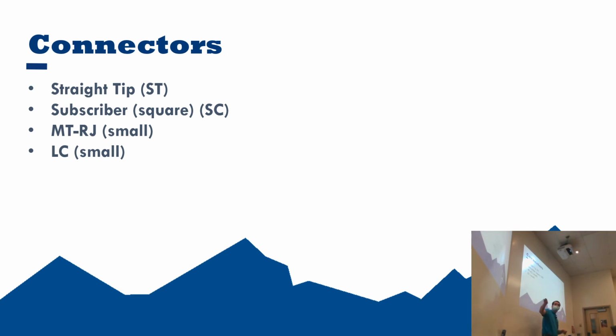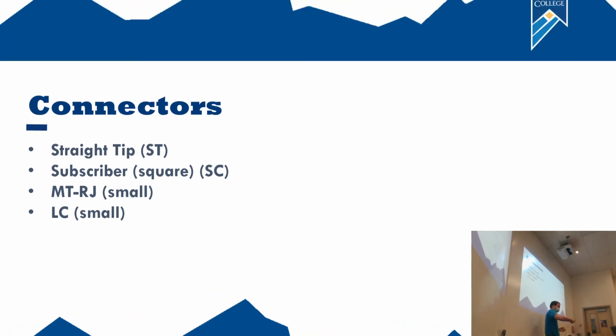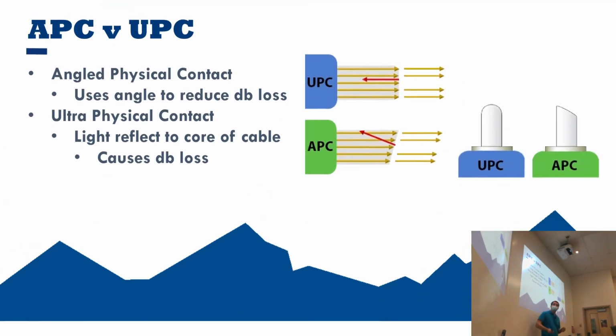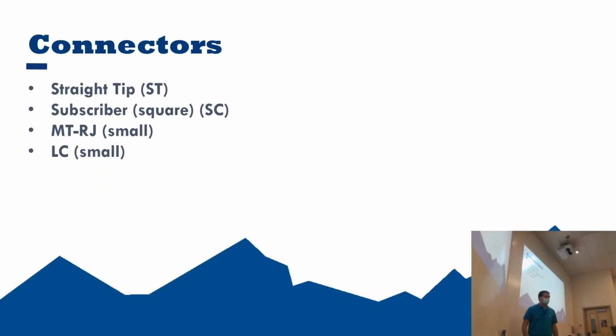These two are definitely older technologies, whereas MTRJ, that's a newer technology, but it's a lot less common for new installations. What you're a lot more likely to see for new installations is LC. It's like this right here, where they're separated strands, but yet it's a single connector. So you basically plug it in and do that. So those are the basic types of connectors.